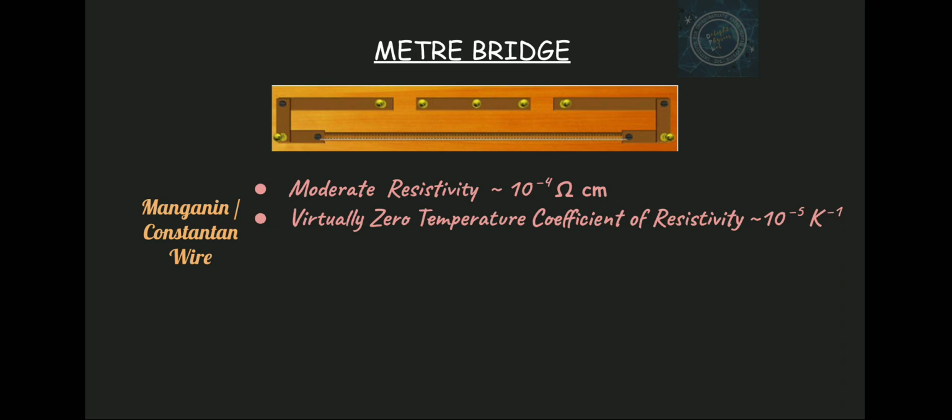What are the other properties it must have? Well, another property that it has is a very low linear thermal expansion coefficient. That is, with heat, you already know that the material expands. So if it expands, of course my null point will again shift perhaps, so that is not allowed, and this material has it in the order of 10 to the minus 6, which is very low.